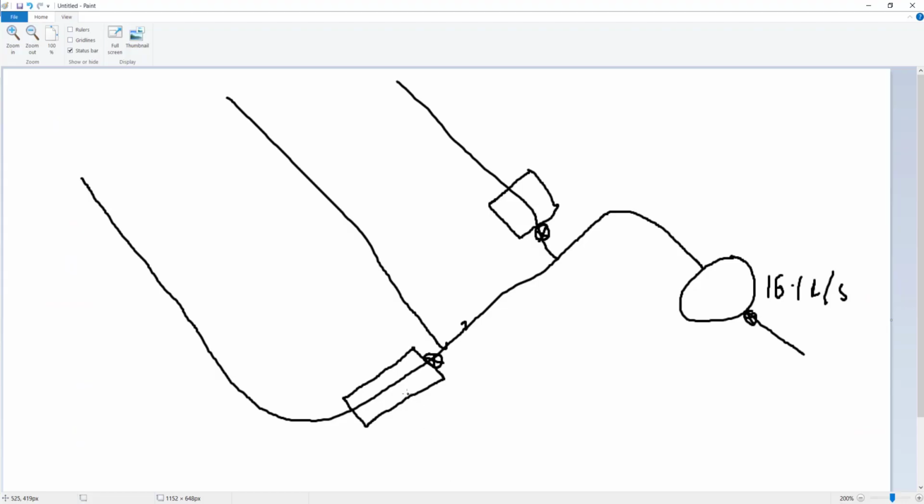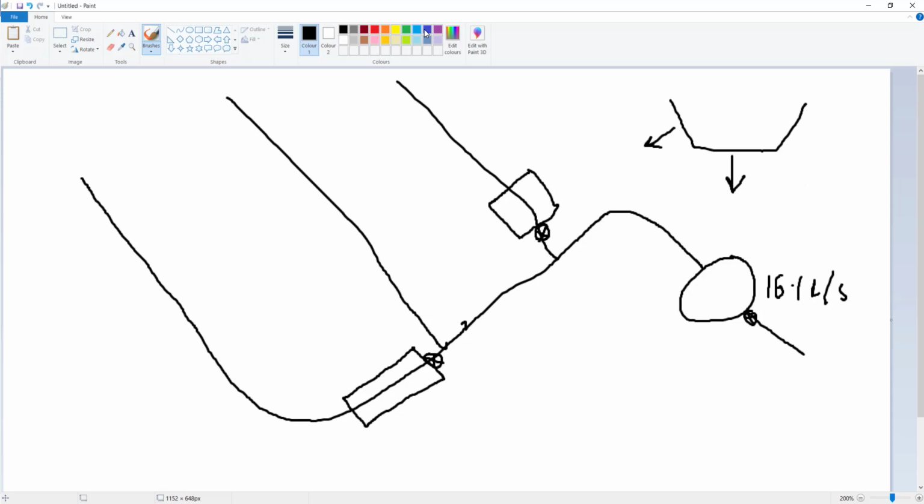Just going back to my whiteboard a second. So we've got the cross section of the swale there. So we're going to have infiltration both out of the base and out of the side. So as the swale fills up, so as we have a water level here, it would expose more of the side and hence more of the infiltration to the swale, like that. Okay.